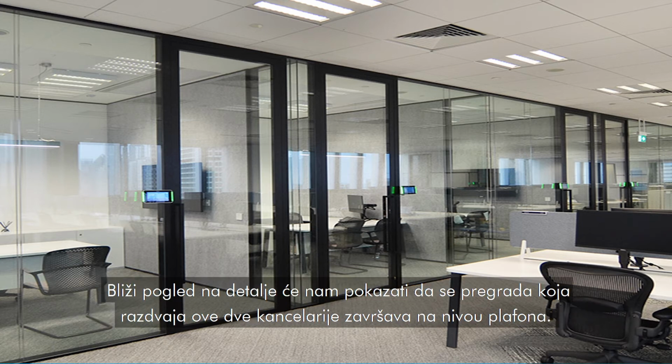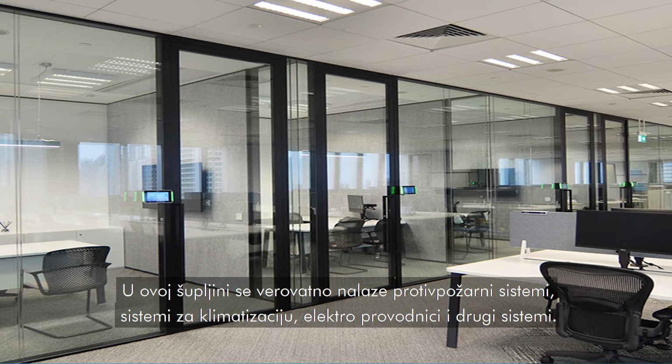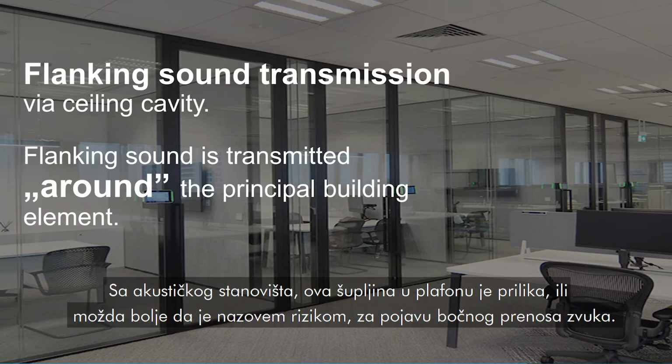A closer look at the details will let us know that the partition which separates these two offices terminates at the ceiling level. If we opened one of these ceiling tiles, there would be a large ceiling cavity expanding across the entire office space. And this ceiling cavity will most likely contain firefighting systems, air conditioning systems, electrical conduits, and other services. From the acoustics point of view, this ceiling cavity is an opportunity, or better to call it a danger, for the phenomenon of flanking sound transmission.